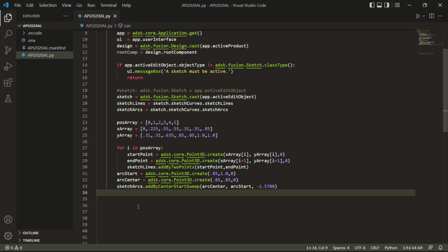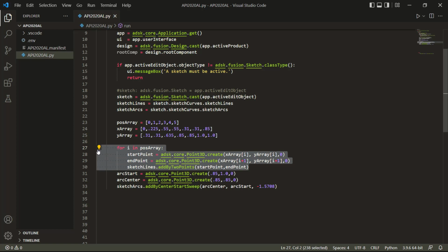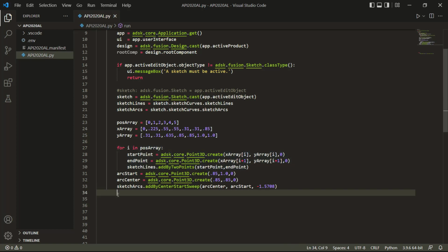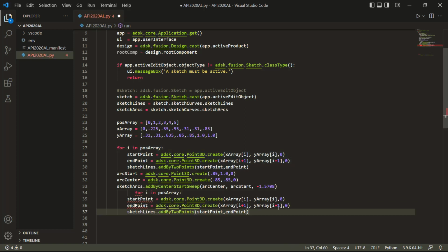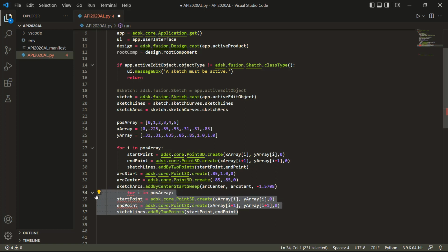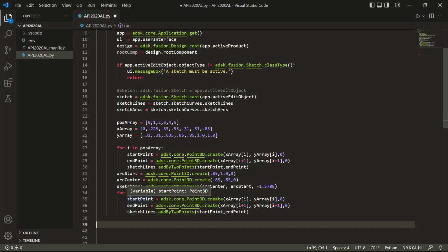So what we really need in order to get a full quarter of our design is this for loop repeated after the arc center. So we're going to come down here and we need to make sure that it's at the correct indentation. So I'm going to do Shift Tab, and then I need to do a Shift Tab in front of this, select all this, and make sure that it's tabbed in, because the spacing, the tabs is all very important whenever we're working in Python.